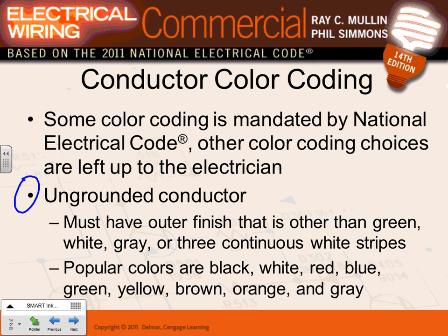If it's 240 three phase, 3-wire, corner grounded, the grounded conductor will be B phase: black, white is the B phase, and red. 120/240 three phase, 4-wire, high leg, so they give you the configuration. And 480/277 will give you brown, gray, orange, yellow, and 480 three phase: brown, orange, yellow. Can you guys highlight this? If you're a designer, these are very, very important.